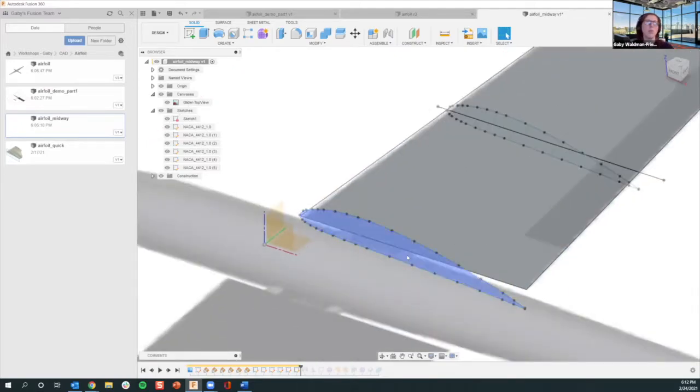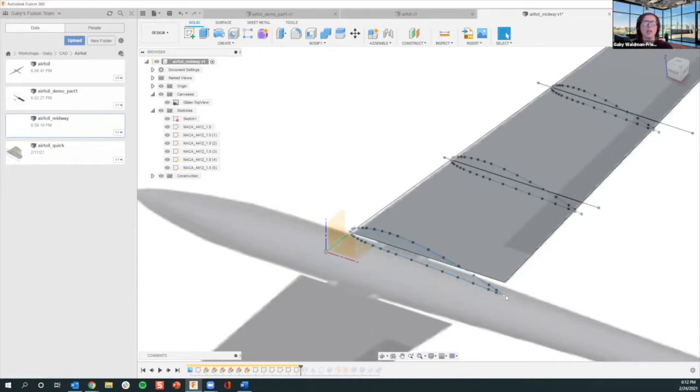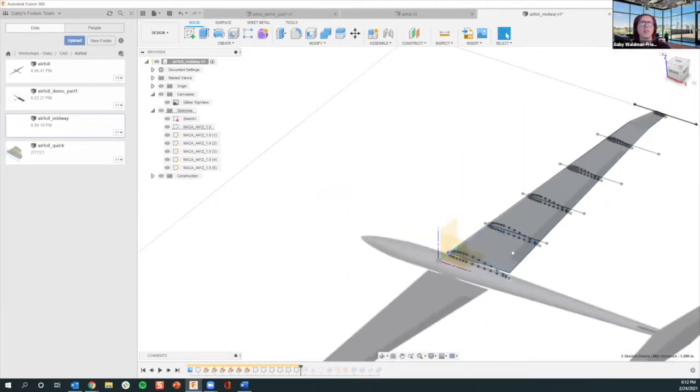And the reason we imported it on each of the planes was because we were able to scale the imported DAT file to the length of the chord. Now the chord is basically the distance from here to the end, so from one tip of the airfoil shape to the other tip of the airfoil shape. As you can see on this wing, that chord length changes as you go down. It's going to get smaller as you get down the wing. So that's why it's important to import a different DAT file for each one that's able to be scaled, versus just copy and pasting the same one over and over again.